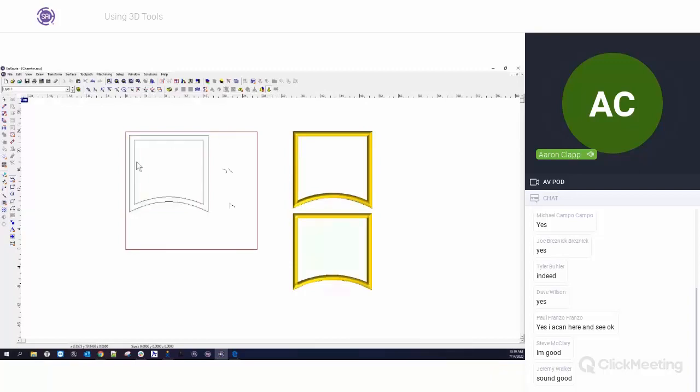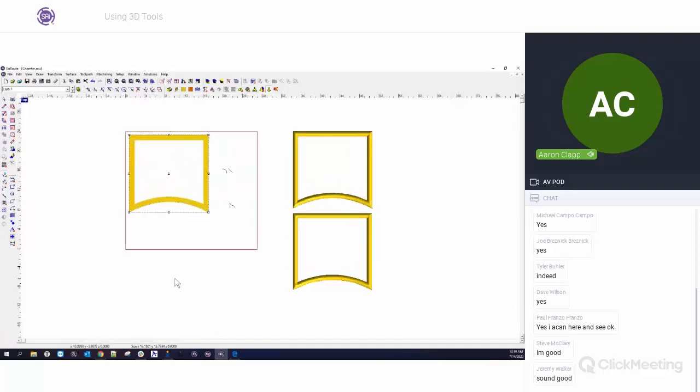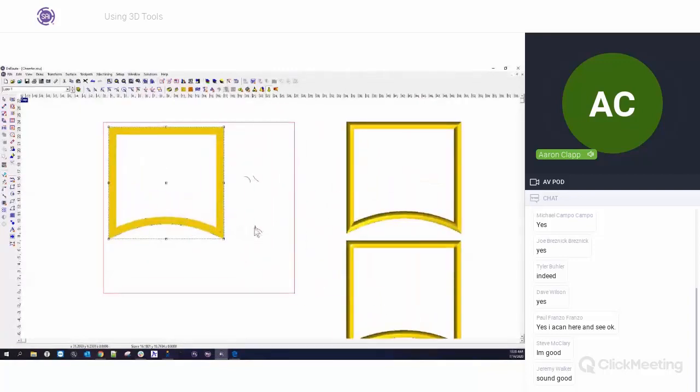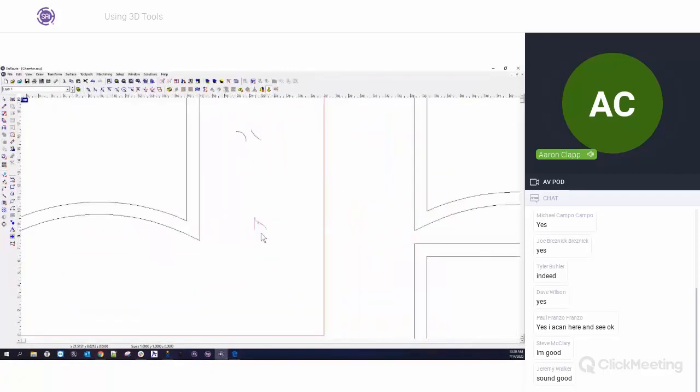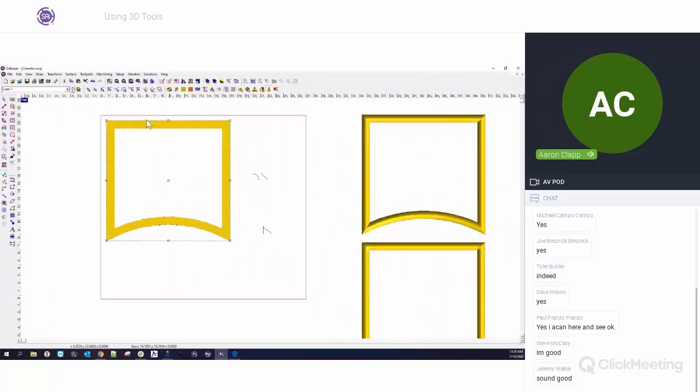I've created this shape right here. And what I've done is I'm going to grab these two objects. We'll go to Surface, Add, create our flat, no thickness relief. And these shapes over here, by the way, on the right, this is what it produces. But we're going to step through the process here. So in this case, I'm going to use this little curvy profile that I made. So I'm going to select my relief.